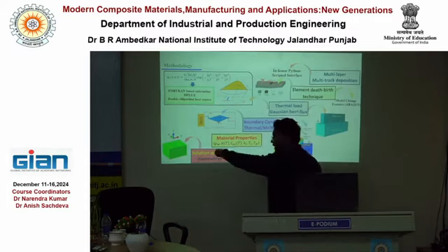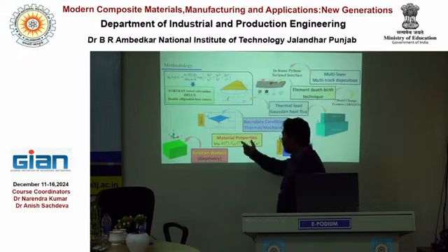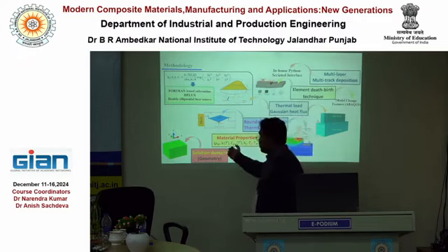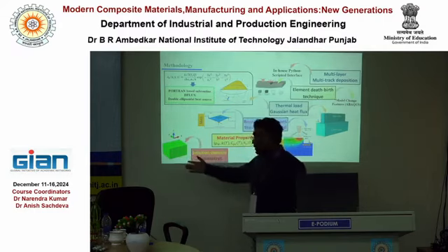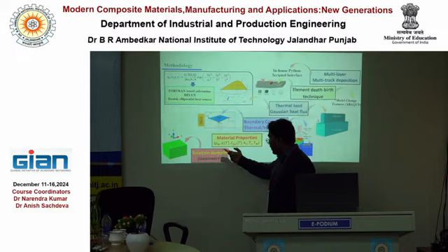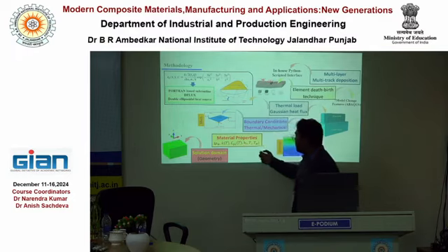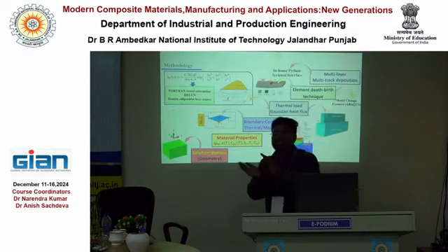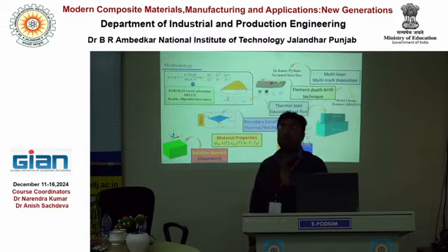So firstly we created a solution domain, or a geometry. Thereafter we implemented the material properties to give the behavioral aspects of the specific material to this fabricated structure: density, thermal conductivity, and specific heat capacity. Thereafter latent heat of fusion, solidus temperature and liquidus temperature. These are the thermophysical properties that play a role if you are thinking of the heat conduction equation or thermal analysis.